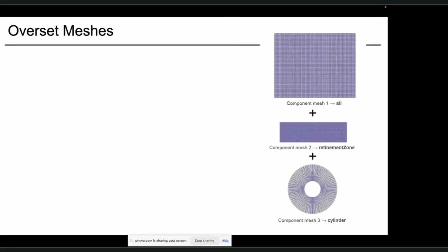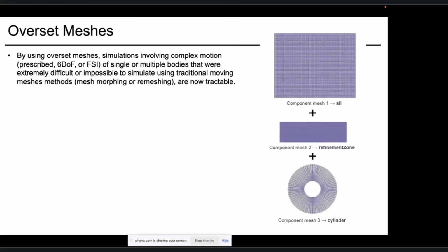So I think we are good to go ahead as we don't have much time left. The second category of the method that we want to explain or show you is the overset method. As I have already mentioned, overset meshes are the approach in which we have multiple component meshes which are disconnected to each other, and some of them are Eulerian and some of them are overset, which moves overlaid on another.